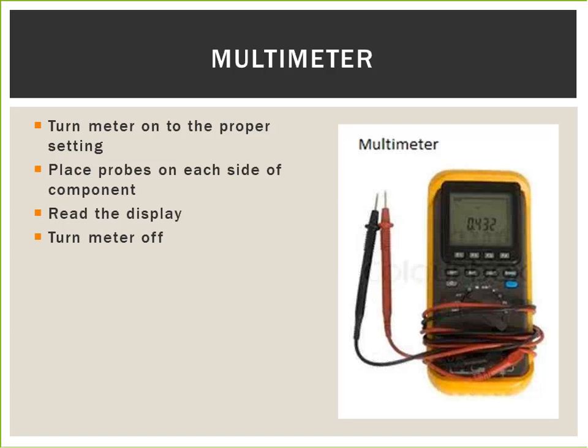Checking diodes is accomplished by setting the multimeter to diode check, which may be symbolized with an arrow against a vertical line. Turn the device off and measure the diode by placing the negative probe on the cathode of the diode, frequently indicated by a stripe around the end of the diode, and the positive probe on the anode, unmarked side. Most multimeters will first make a tone, like when indicating continuity, and then display the voltage drop across the diode. This varies with the diode type, but it is typically between 0.5 and 0.75 volts.